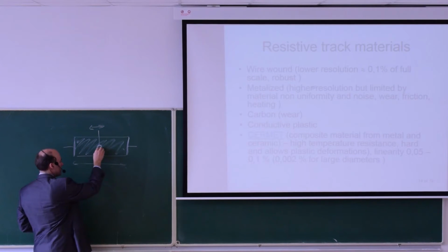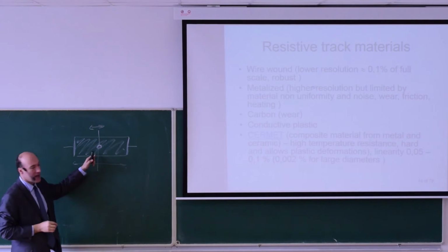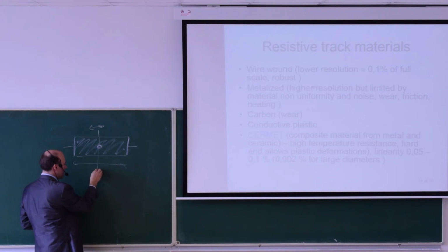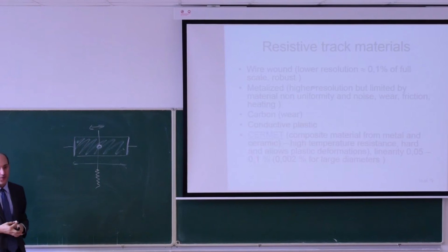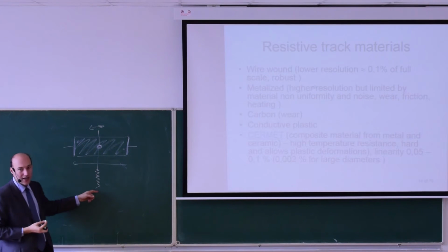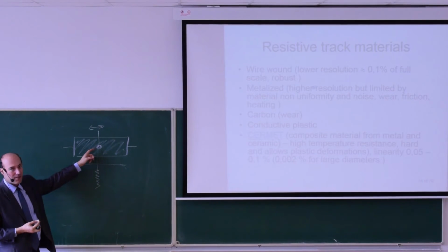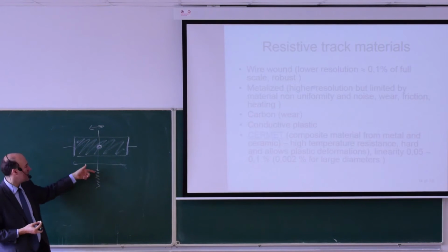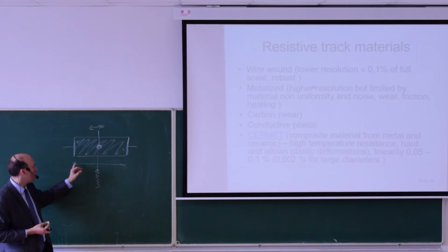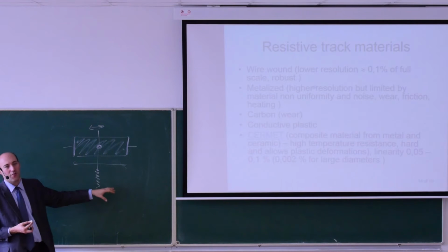But what if I stay in one position, and to this position I superimpose some vibrations? Then this can damage the layer, because it has only so many cycles that this layer would last. So all this arrangement with the layers typically has this problem with vibrations. If you're moving in the whole range, then it's not a problem at all.